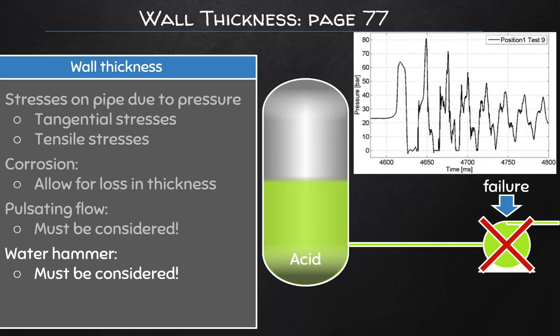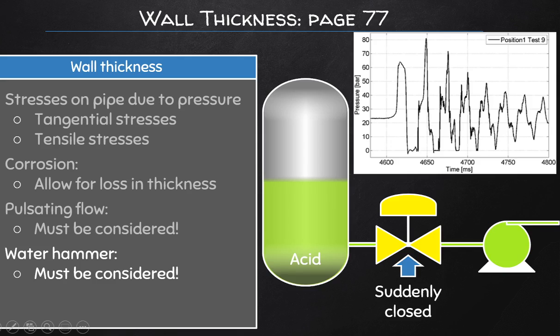And if you are able to locate the upstream pipeline, or even the downstream one as well, watch what happens to it. Usually the pipe will vibrate so violently that it will make a strong noise, a hammer, and it will hammer itself back and forth. And if this occurs too many times, the pipeline will eventually rupture. So it usually goes ka ka ka. Alright, another way that water hammer can occur, other than a pump going off,